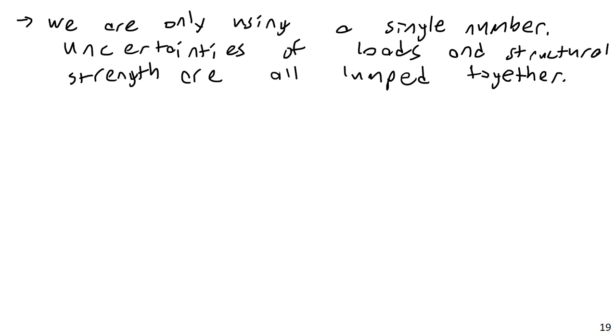It's not going to fail. It's not going to collapse. But what tends to happen is, at least on average compared to LRFD, theoretically at least, you end up with something that ends up being heavier than it needs to be, and more inefficient than it otherwise could be. So ASD does not result in unsafe structures. Rather, it usually ends up with structures that are over-designed a bit.